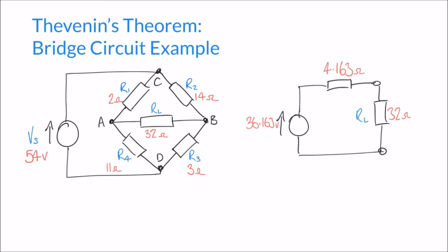And so the current that's going to flow in this circuit, I, is equal to Ohm's law, V over R. But in this case, we have two resistances. We have our load resistor and we have our Thevenin resistor, both in series. So we can say that V, in this case, we're using our Thevenin voltage in this particular circuit.